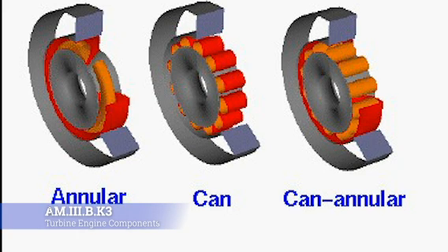Now there's a fourth type, the reverse flow combustor. Reverse flow combustors are a type of combustor in which the air from the compressor enters the combustor outer case and reverses its direction as it flows into the inner liner, and again reverses its direction before it flows through the turbine. Reverse flow combustors are used where the engine length is critical. For instance, the helicopter engine I used to work on was a reverse flow combustor type, and you'll see that in places where you need to squish the engine together. You'll have that reverse flow combustor type where the can is more centralized.